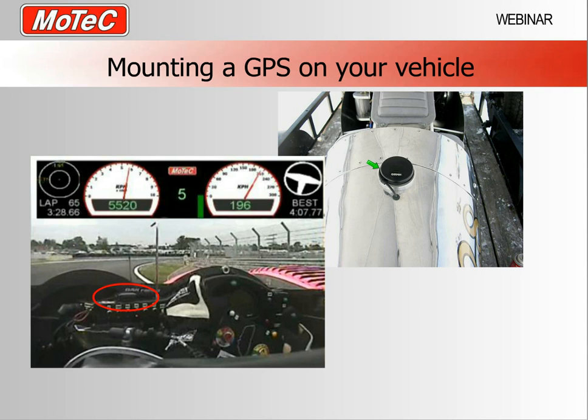So we recommend that you always mount your GPS external to the car and on the roof of the car. So don't place your high resolution, high speed GPS on the dashboard or the back parcel shelf of your race car and expect to get good GPS resolution. You need to place it generally on the outside of the vehicle, and we do prefer that you place it on a metal disc that is larger than the size of the GPS. The metal disc helps stop reflected GPS data being received through the bottom of the GPS unit. The metal disc means that only GPS signals that are directly from above the unit will actually be received.